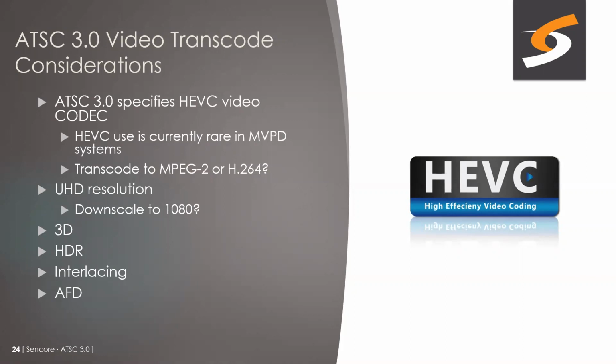Interlacing is another question. Interlacing was a question early on in HEVC. Some of the early standards versions of that didn't even support it. Seems like it's kind of worked its way in again. But many MVPD systems rely on 1080i signals, so a transcoder may have to de-interlace or add interlacing depending on the support needed.